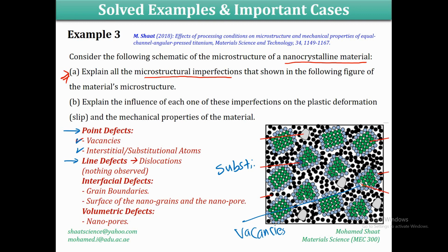It means that an irregularity in the crystal structure or the atomic distribution doesn't necessarily indicate a dislocation. A dislocation requires an extra plane that terminates inside the grain to be qualified as an edge dislocation. So if we try to observe any edge dislocation, probably we're going to find there is no edge dislocation that we can observe from this representation, but simply I could include any dislocation.